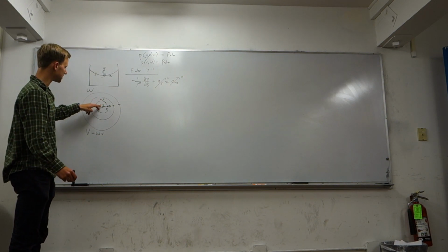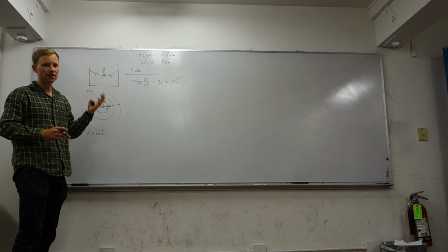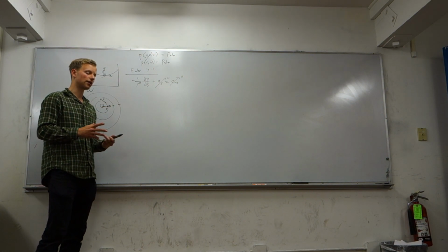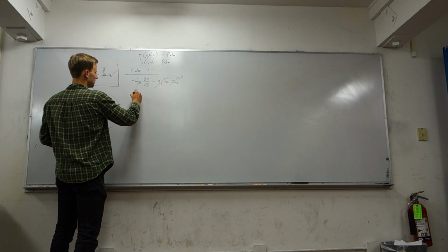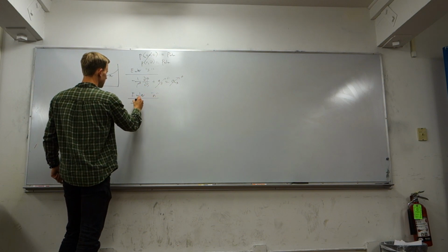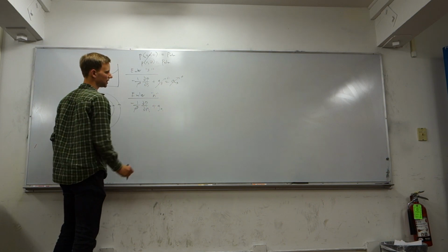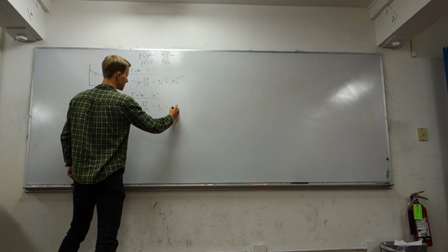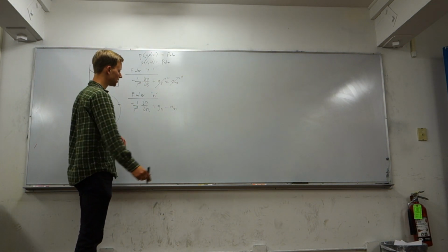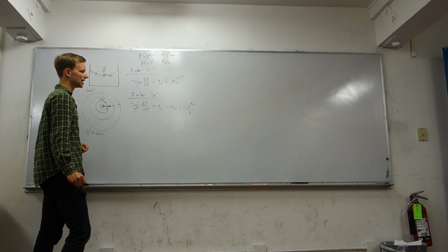So to find the pressure dependence emanating outward from the center, we're going to want to use the Euler N equation. Anytime we have curved streamlines and we're looking for an equation for pressure across those streamlines, Euler N is an appropriate equation to use. Euler N has the exact same formulation, -1/ρ dp/dn plus the component of gravity in the n direction is equal to the acceleration in the n direction. Since we have curved streamlines, we can no longer say that this acceleration is 0. It's equal to negative v squared over the instantaneous radius of curvature.